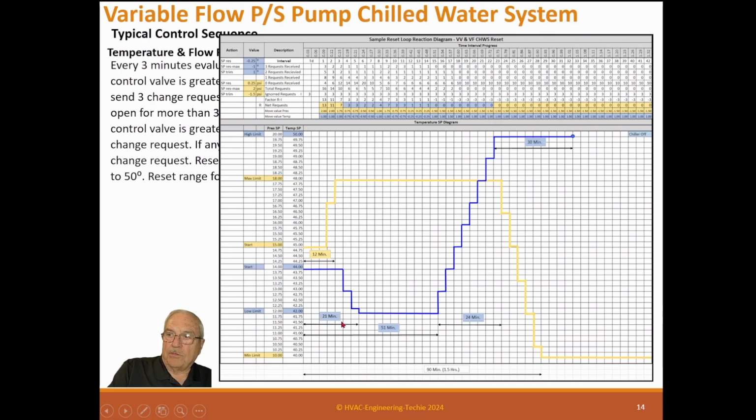And then my main concern was the minutes here. 21 minutes to start to get the lowest temperature, and then 24 minutes to get the highest temperature. So those are all within this half-hour realm that I like to see. Now, maybe, from 42 to 50, you don't need a half hour, but basically, if it'll do that, it'll work out. Remember, normally, this just inches along. It just makes a change. It doesn't change super quick like I'm showing it, but I'm driving it to its extremes to make sure this is responsive enough for the user.